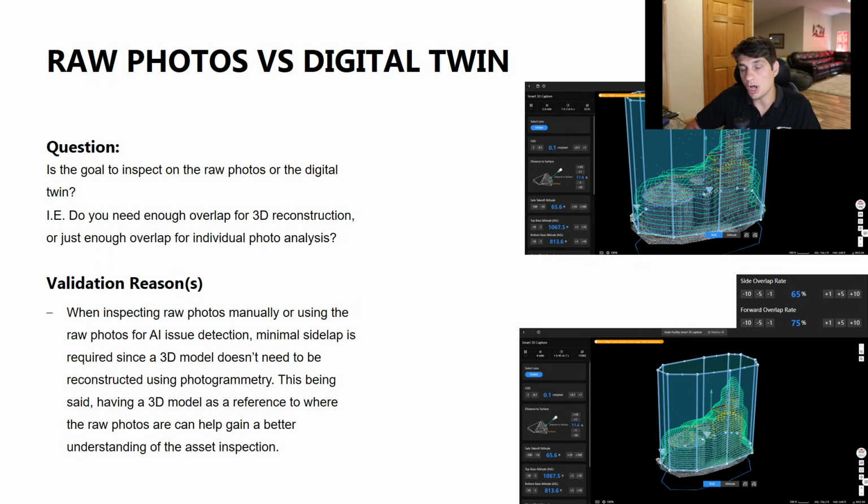So overall, you can see, once again, we're pulling up the grain facility instance. If I'm capturing the entire site, that's 11,000 photos and an hour and 45 minutes of flight time, which can take multiple hours of just being on site. But if I bump down the side lap and front lap options, I'm down to just an hour of capture with 6,500 photos. So really ask yourself, what is the use for these photos? 3D model representation or raw photo inspection?